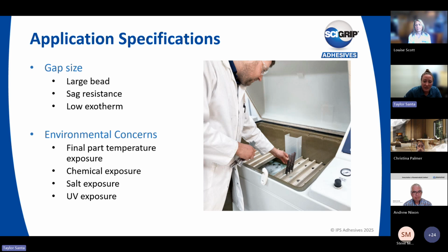The SG100 series includes certain ingredients to ensure bright white colors don't fade when exposed to UV over the lifetime of a part. This is ideal then for exterior bonding of bright white gel coat fiberglass bonding. The SG230 series is used all over marine manufacturing, both in fresh and salt water. This adhesive has been tested and will withstand a lifetime of salt spray exposure. So be sure to know what exposures your parts will have after they're actually bonded together in order to have a good lifetime bond.